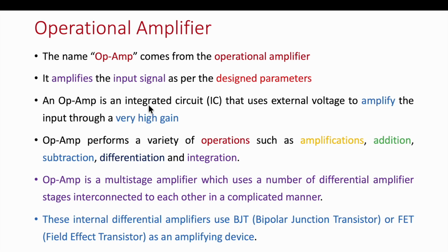An op amp is an integrated circuit that uses external voltage to amplify the input through a very high gain. An op amp performs a variety of operations: amplification, additions, subtractions, differentiations and integrations. An op amp is a multi-stage amplifier which uses a number of differential amplifier stages interconnected to each other in a complicated manner. These internal differential amplifiers use bipolar junction transistors or field effect transistors as an amplifying device.